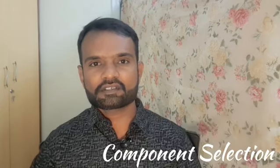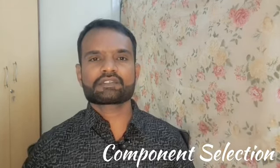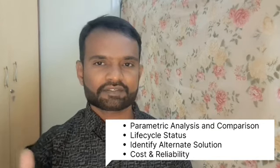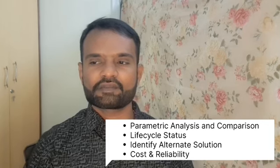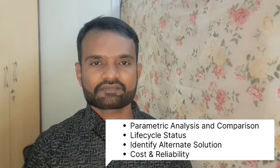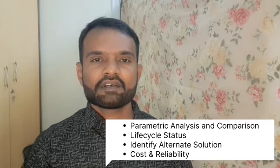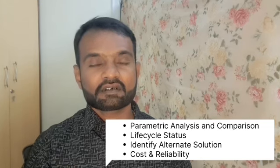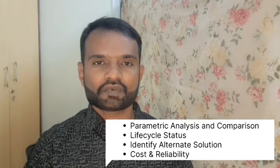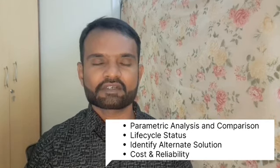When it comes to component selection, any component we select, we understand the requirement at system level, and then we have to break it down to component level. We have to see what parameters need to be analyzed according to the design spec. That is the topmost priority for component selection. Alongside, we need to understand the component life cycle, how long it is available in the market. If it suddenly becomes obsolete, NRND, or declines in the near future, then we need to see if there is an easy way to find a substitute over a period of time.